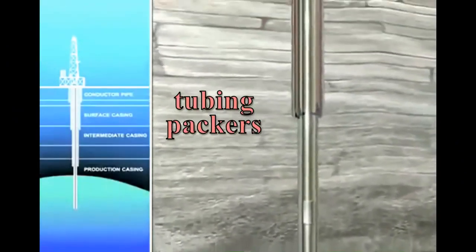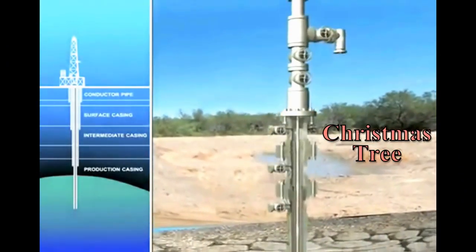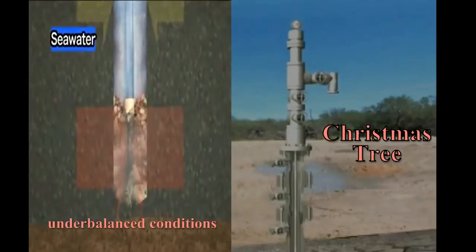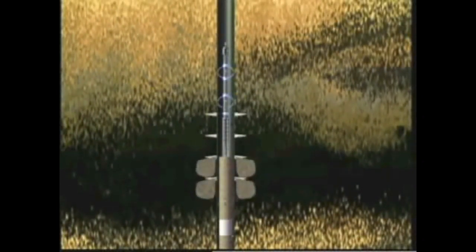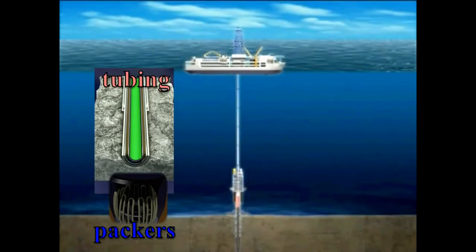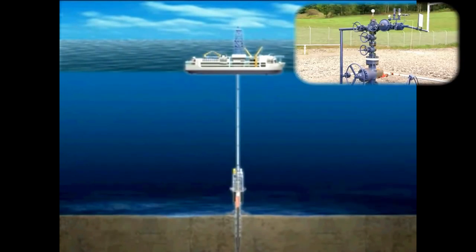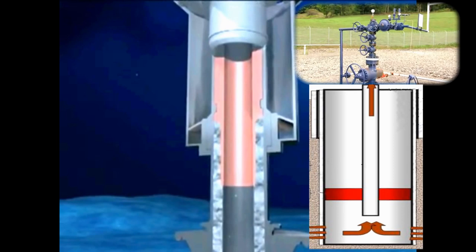This means that the well will be outfitted with tubing, packers, and the Christmas tree to better accommodate perforating in preferred underbalanced conditions. In addition, many of the subsequent well treatment processes described in the next segment of this chapter are optimally done after the well has been outfitted with these three components. They include the wellhead and the various processes of preparing a well for production and will be discussed here.